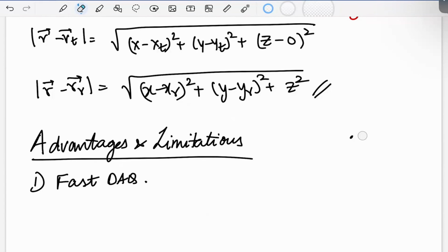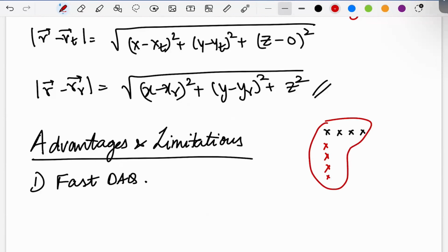It's a real aperture. You can also even combine SAR and MIMO. So you can have, for example, 4 transmitters, 4 receivers. You collect all of this data, and then you move this whole thing there. Then you collect all the data there, and then you move it here, and you collect all the data and you move it here, and so on.